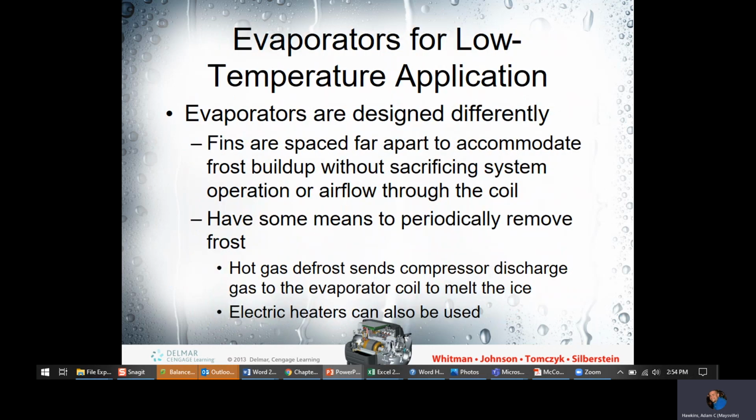Frost on the evaporator. This is something else that you might run into. On air conditioning, there should never be ice on the evaporator. It should operate at 40 degrees or thereabouts, and then you're going to be running another 10 degrees of superheat on the coil, on the metal. So by the time it leaves, it should be 50 degrees. So there's really no reason that you should ever have a freezing coil. What can cause a freezing coil is usually low airflow, dirty filter, dirty coils, a fan kicking out, something like that. Doors off the unit, you left it off while you were working on it.